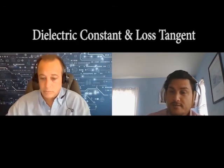So as you know, you put antennas next to high dielectric constant materials such as our body or water. The higher the dielectric constant of the antenna itself, the less sensitive it is to detuning. So we will use a higher dielectric constant. And also usually our loss tangents are pretty low. We're low loss. That's why we can achieve pretty decent gain in a very small form factor.